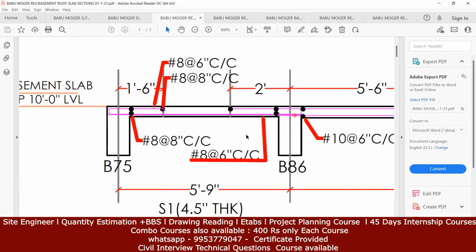So what is given here? It is mentioned in the bottom, what kind of reinforcement. You can see the marking done here. Two markings. One, you can see that dark circle, isn't it? So that is a distribution steel. I mean, not a distribution steel, because if it is a two-way slab, both are main steel. But for our understanding, I'll use a term called distribution. But remember, if it is a two-way slab, both are main reinforcement.